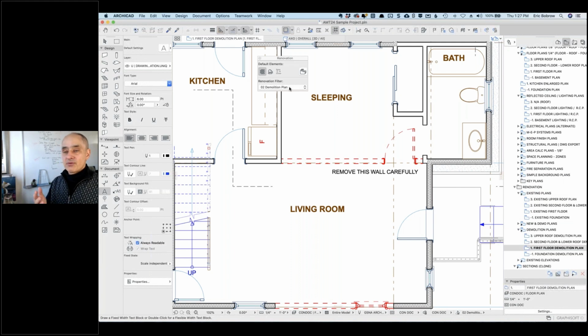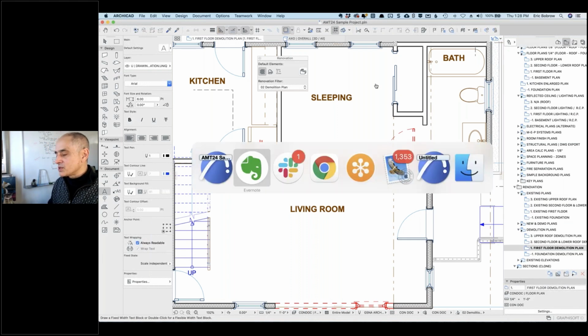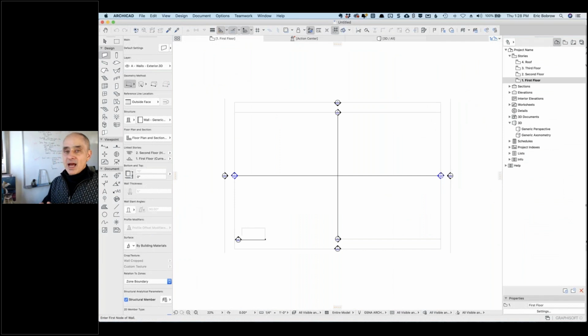And if you wanted to have a wall layer for scheme 1 and furniture for scheme 1 and electrical for scheme 1, then you might need several layers for scheme 1 and several layers for scheme 2. And then your layer combinations get potentially much more complicated. So here is a way that you can deal with this more easily. It has some limitations, but it does handle some cases so elegantly that it's absolutely worth knowing.